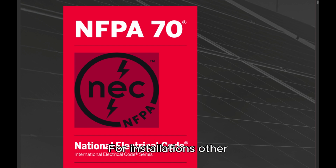For installations other than equipment as described in 110.31(D), a wall, screen, or fence shall be used to enclose an outdoor electrical installation to deter access by persons who are not qualified. A fence shall not be less than 2.1 meters (7 feet) in height or a combination of 1.8 meters (6 feet) or more of fence fabric and a 300 millimeter (1 foot) or more extension, utilizing 3 or more strands of barbed wire or equivalent. The distance from the fence to live parts shall be not less than given in Table 110.31. Informational note: See Article 450 for construction requirements for transformer vaults.